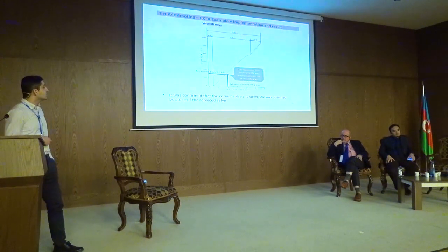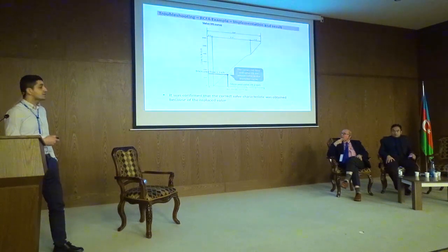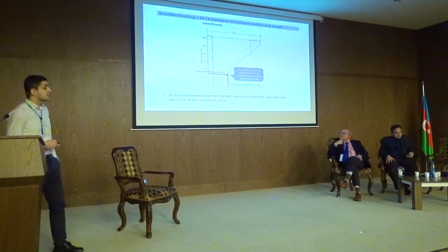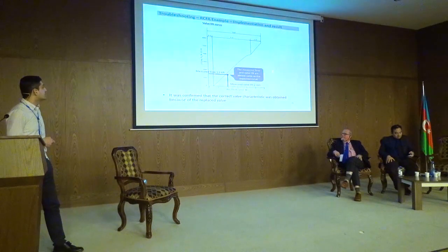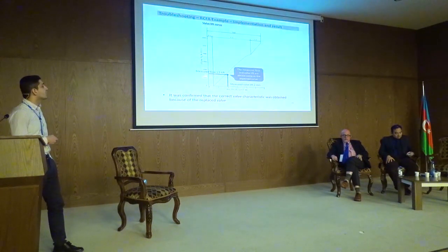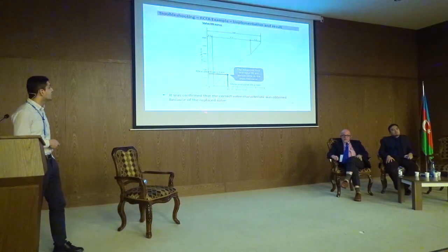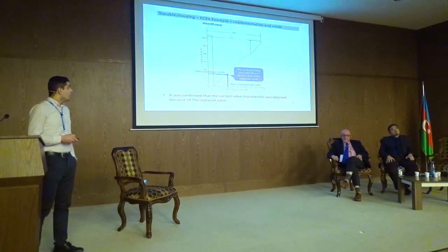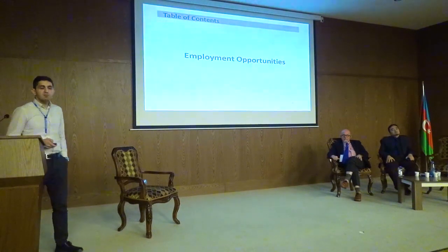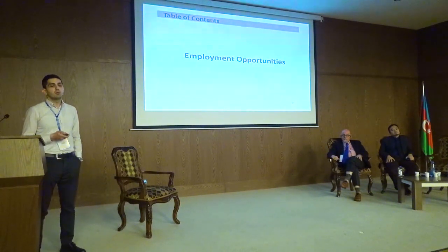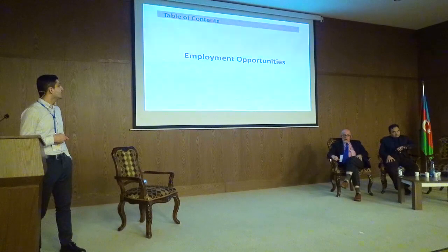According to the results of the turbine solo run at the later stage, we could achieve the results that we wanted. At 2 millimeter valve lift, we were already achieving 1.5 tons per hour flow rate of steam.